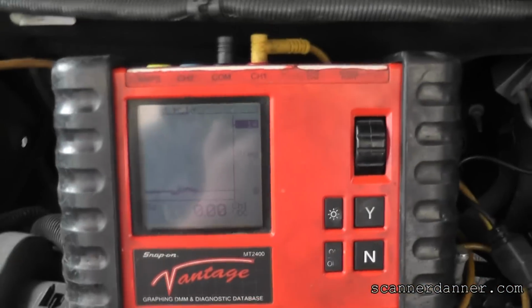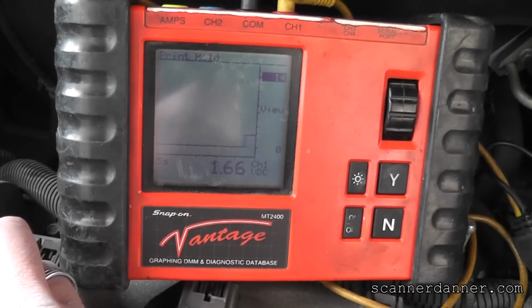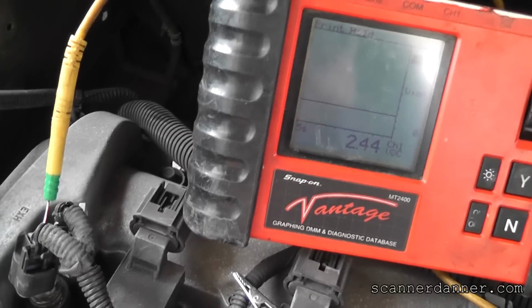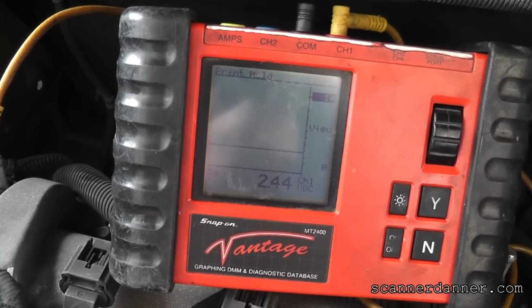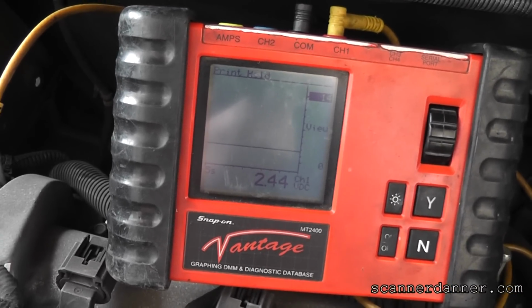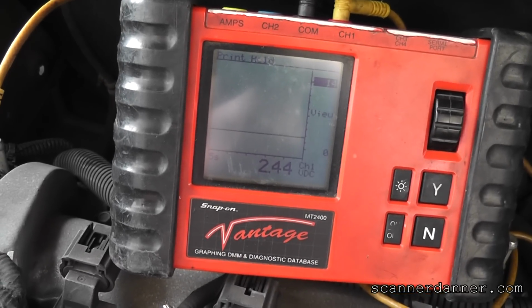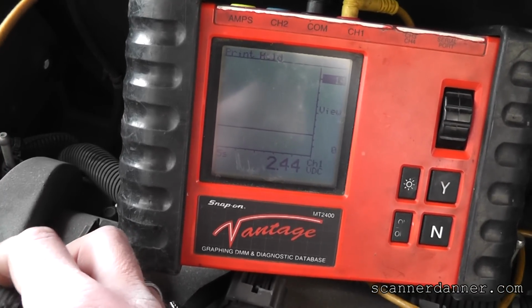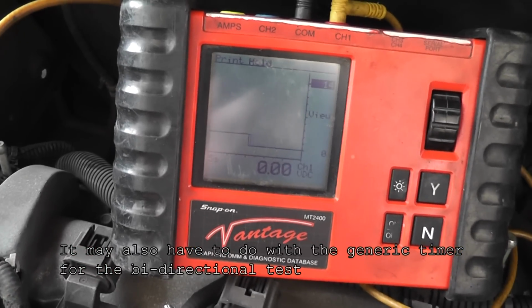All right. Notice the steady 0 volt. Unplug the connector. Oh, there's 2.4 volts now. Well, it was at 0.93 before. What changed? I don't know. Maybe my ground connection on my meter? I don't think so. That bias changed on me. It was 0.9 before, and now it's 2.4. And it may have to do with fault codes in memory and it changing things. Well, maybe that's why the manufacturer's not giving it to us, because it's not consistent.